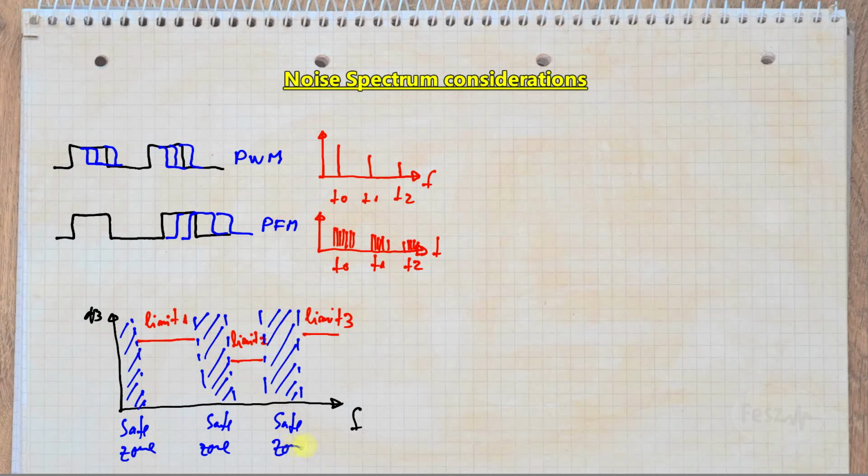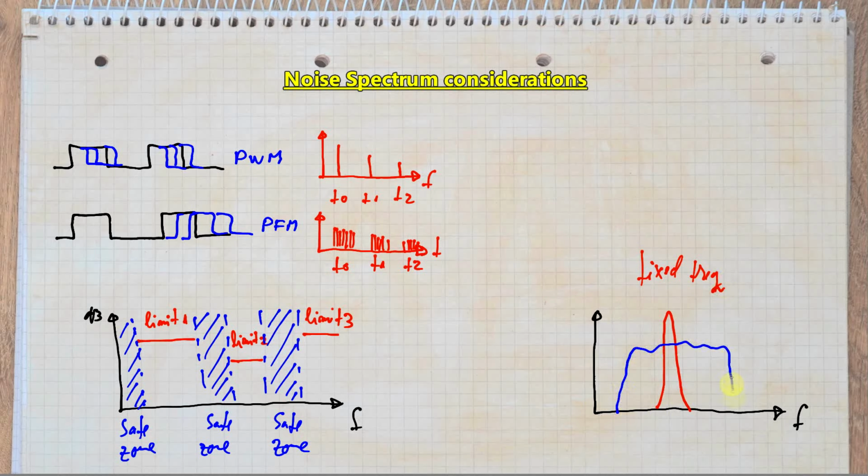This analysis can be taken one step further, and special attention can also be placed on the first few harmonics. The last aspect of the oscillator that needs to be considered is the implementation of some form of frequency modulation. So various ICs will implement different strategies for this. Two common names that you will find are spread spectrum clock generation and frequency dithering, but the fundamental idea here is that if your oscillator does not have a fixed frequency, the noise energy can also be spread out. This in effect makes the emission smaller, thus being able to help you pass emission tests without actually reducing the total amount of noise that you are generating.